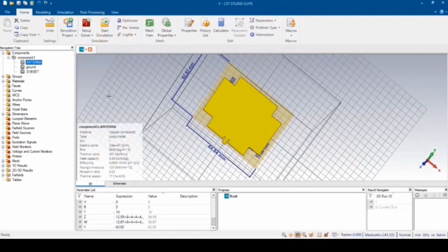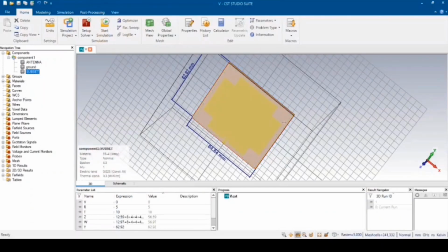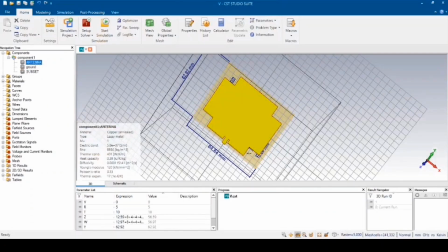The shape of the patch used here is circular. The microstrip patch monopole is most commonly used in different shapes because it produces linear polarization and is also easy to fabricate. Also, it gives low cross polarization. The microstrip patch is fed by a microstrip feed, whose inner conductor is extended up to the patch through the substrate and is soldered to the metallic patch.